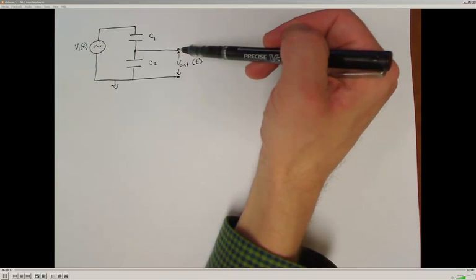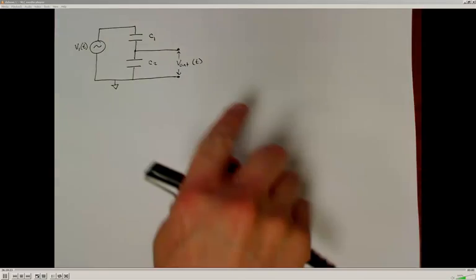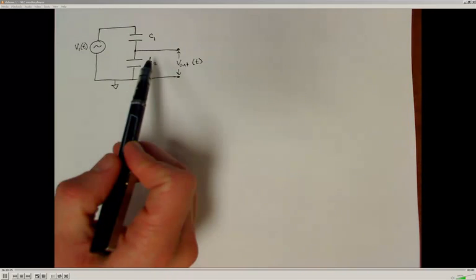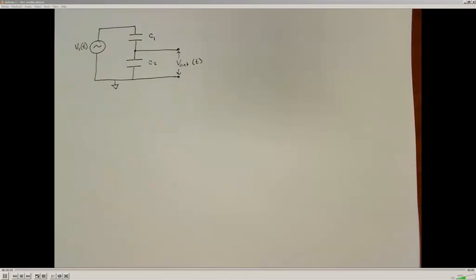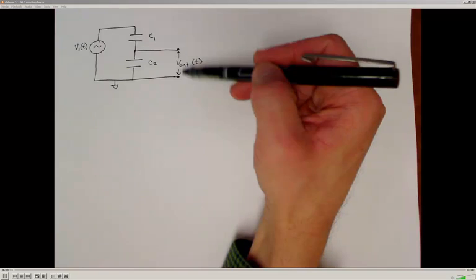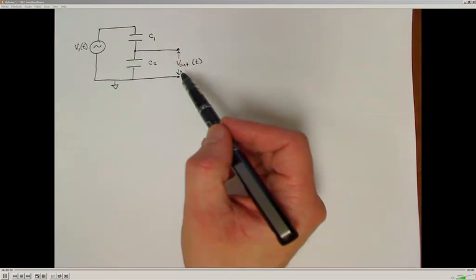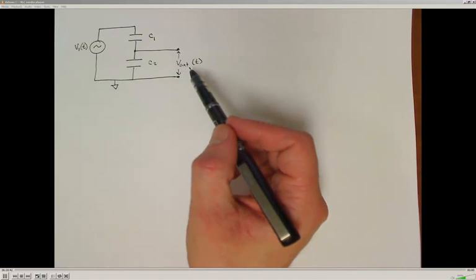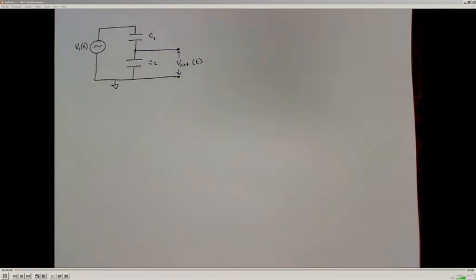So your iPhones, ATM screens, things like that use clear capacitive elements, and when you touch your finger to them, it changes the capacitance in one of the legs of this voltage divider. And we're going to develop an equation, or develop the relationship between the input voltage and the output voltage, and see how this can be used to monitor for touchscreen types of interfaces.